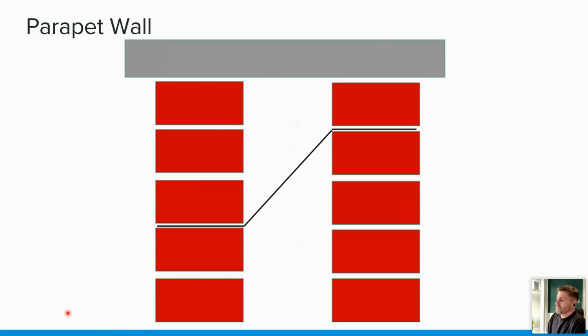So when we're waterproofing a system, if we're going to be thermally upgrading, if our waterproofing is going to be going over the top of here, then obviously we're going to be blocking off those weep holes. So then any water that gets into here will go down behind our waterproofing system. So it's a very important consideration. So one way to get around it is to make this cavity tray redundant.